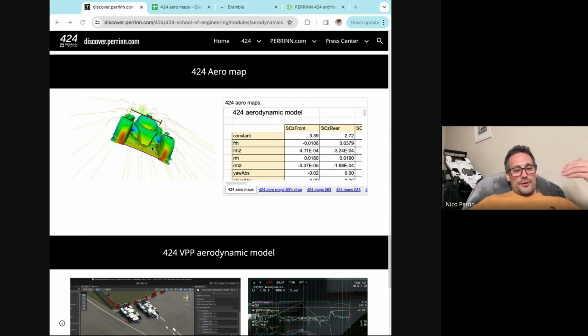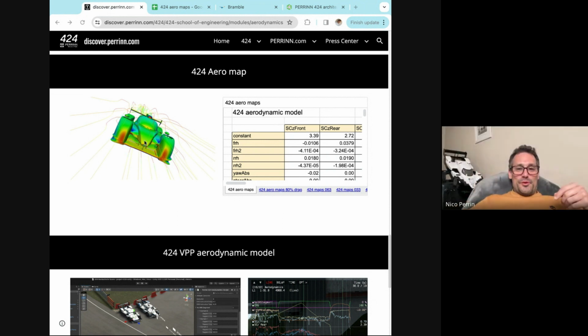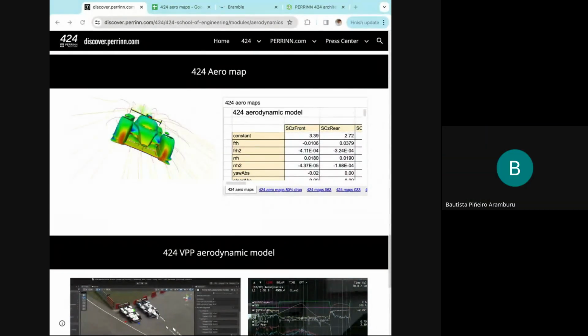And coming from F1, I wanted a front wing that was uncovered. It was a concept that I believed in. And to be fair, you see these blue areas in the corners? When you move that leading edge backwards like I did, it creates a very aggressive flow. That's because there's a lot of high pressure in front, and then it pushes the flow nearly vertical, and then you have to go around that bodywork, trying to make it follow the bodywork towards the suspension.